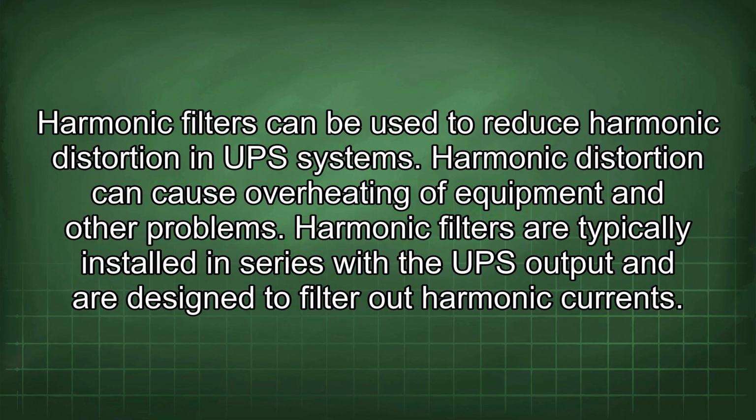Harmonic filters can be used to reduce harmonic distortion in UPS systems. Harmonic distortion can cause overheating of equipment and other problems. Harmonic filters are typically installed in series with the UPS output and are designed to filter out harmonic currents.